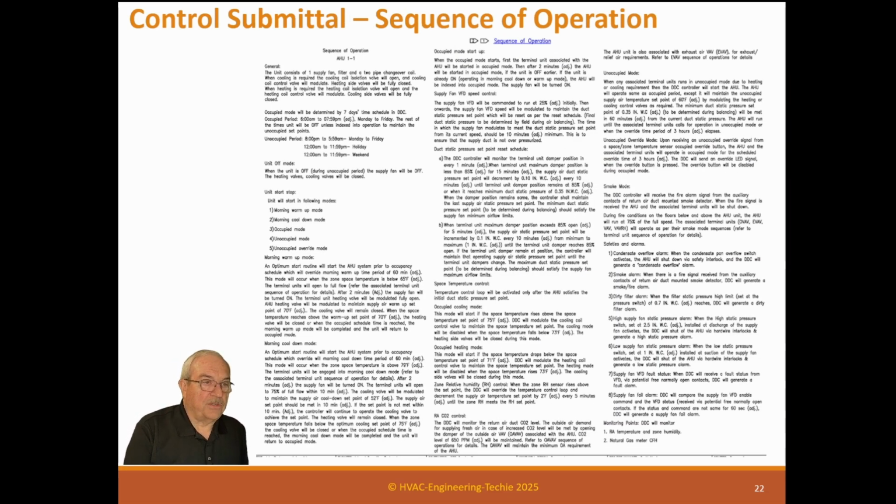Now, the sequence of operation is intended to be the contractor's sequence of operation, not the engineer's sequence of operation. Let me explain. The engineer writes a sequence of operation of how he wants the system to work in plain English. Okay? A programmer does not program in English. He programs in his system's syntax, which means he has to have a lot of things that an engineer doesn't need to put in there, like exit times, exit delay timers, exit points, entrance points, reset sequences exactly. A lot of things that the engineer does not need to detail.